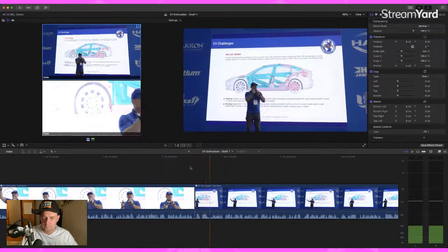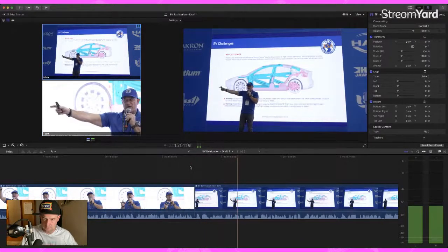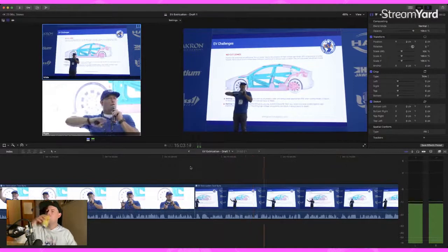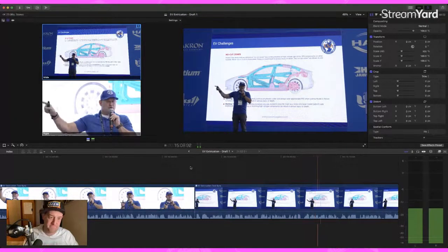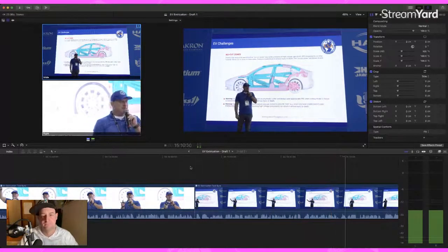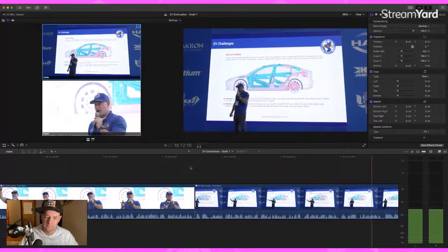There's always stranded energy on the high voltage battery pack and on the high voltage cable, no matter what shutdown processes you do. So if you cut that, you are probably going to interact with 400 volts minimum. Everybody follow that? That's not going to be a desirable outcome.